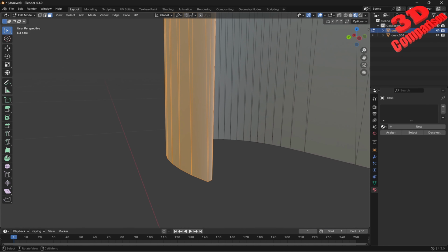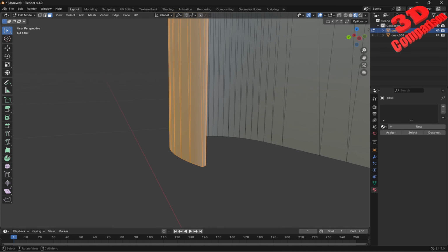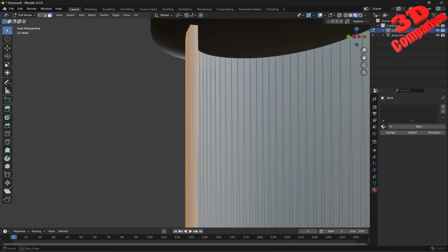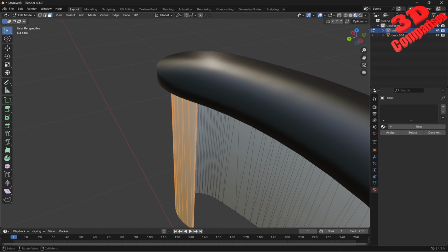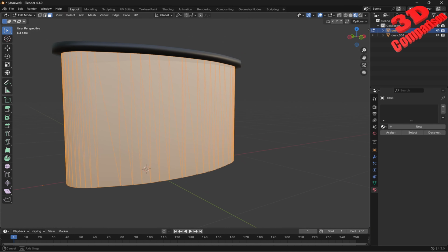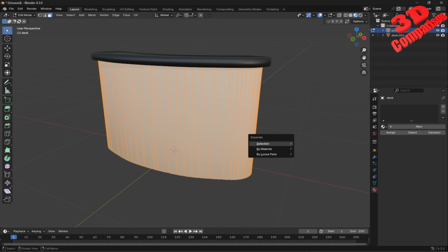And keep in mind that since this is an STL, we're going to have a triangulated model. So this face will have one triangle with an edge over here and a vertex all the way at the top. And that should be in the other direction as well. So this will be the selection. With this selected, I will press P and I will separate the selection.